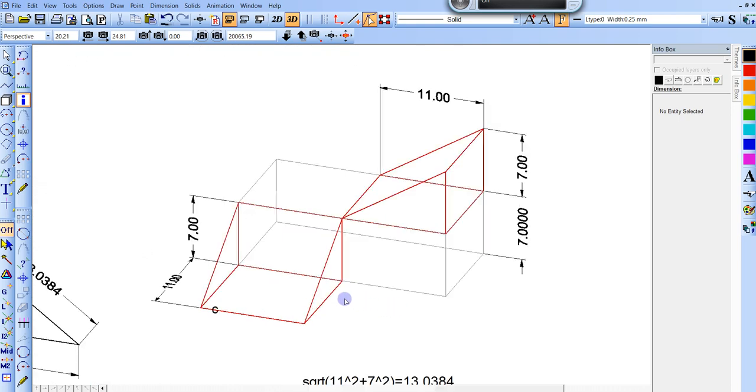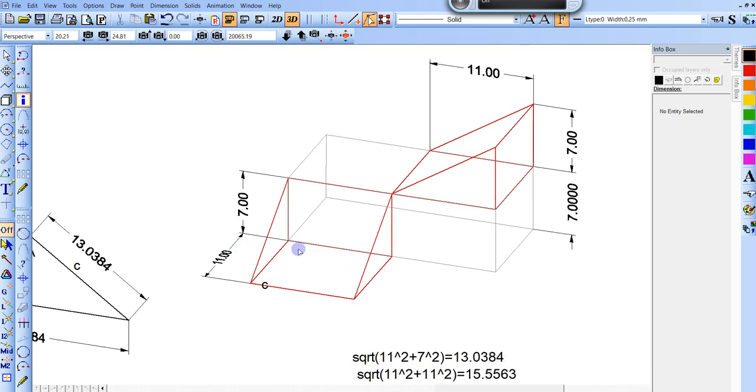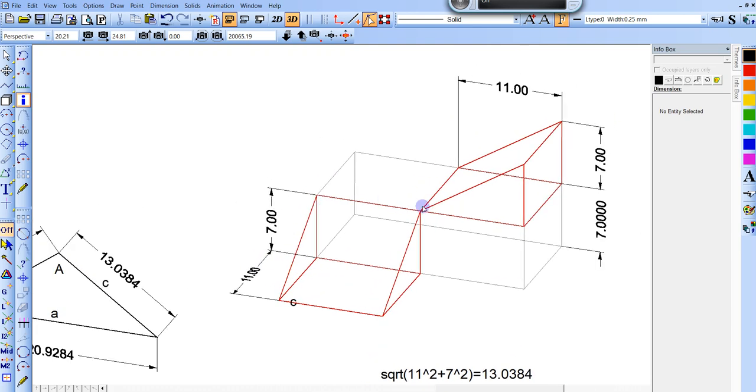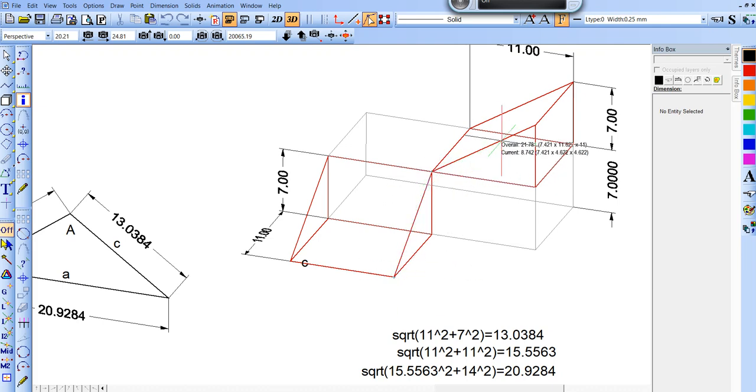You're going to need that if you're going to prefabricate the stanchions. Here we go with the calculation for that 106. You don't have the 3D computer. Then you do your rise and run to a landing, and a rise and run to a landing. It's just one tread, because all you're looking for is the angle. So we're looking for this angle here. We need this diagonal, this one here. Let's just draw the triangle. We need that leg, which is going to be the same, and then we need this long diagonal here.